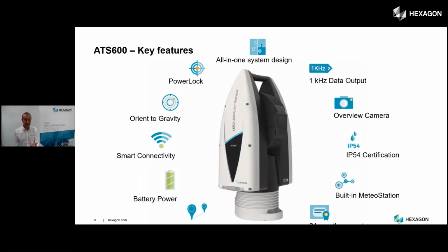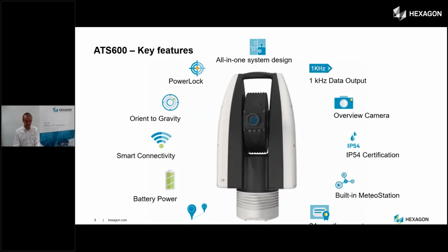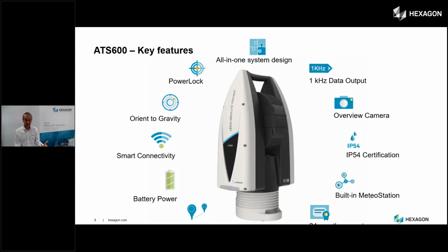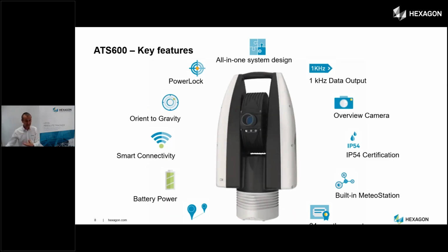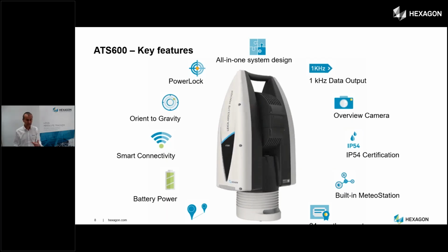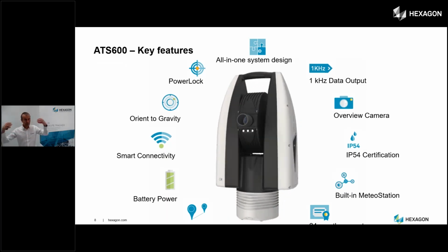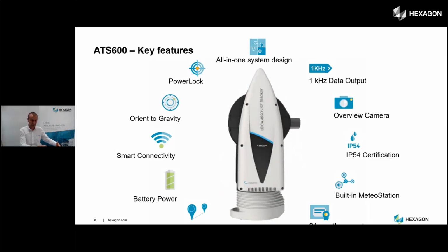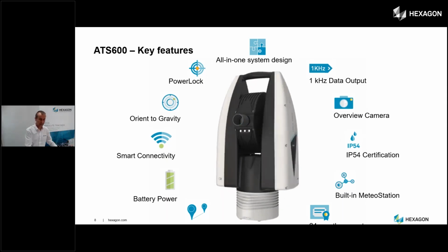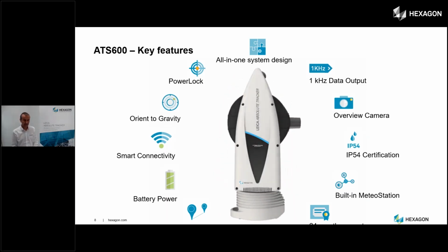Some other characteristics of laser trackers as such. So systems are very mobile. The 8403, 7.5 kilograms, can measure a volume up to 160 meters. All trackers can be used on battery power. And especially for roller alignment, think about a large machine where you want to put the tracker on the tripod. It's very, very useful if the system is used on battery power.